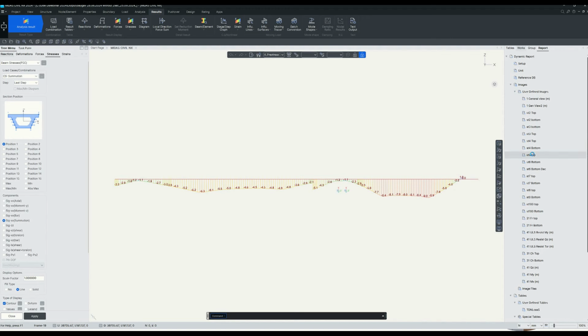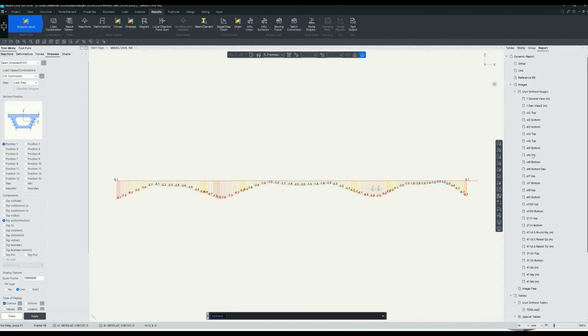Stage 6, MIDAS shows us stresses at top and at the bottom. This is the last stage where we stress tendons. For example, here we do not exceed the permissible values of tensile stresses at the bottom fiber near the support section. Just if we have some bigger values, then I can check at the level of decompression.